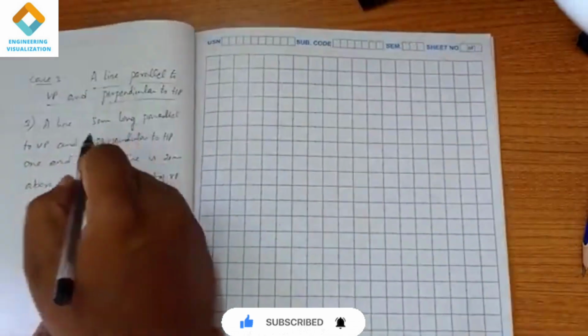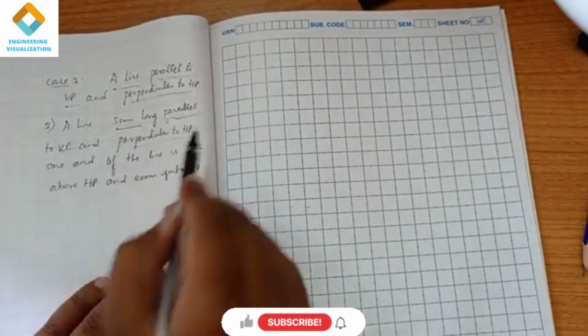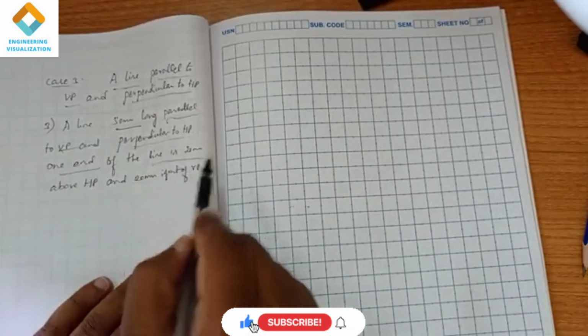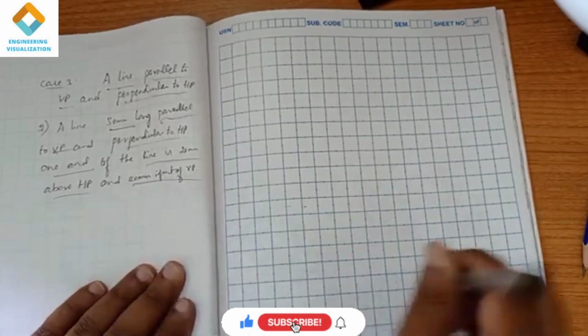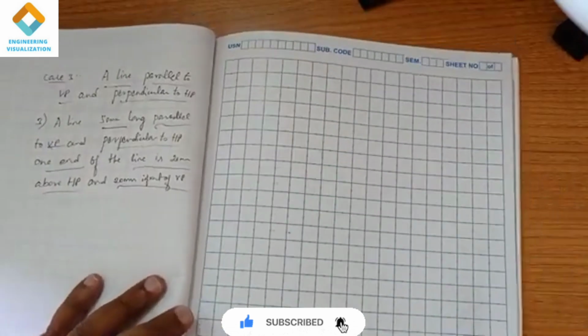We have to draw a line of length 50 mm. It is parallel to VP and perpendicular to HP. One end of the line is 20 mm above HP and 20 mm in front of VP. First we are going to draw an XY line here.